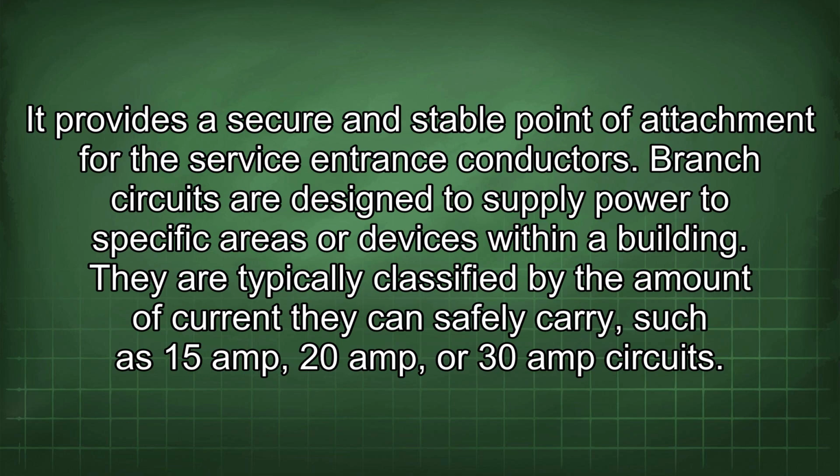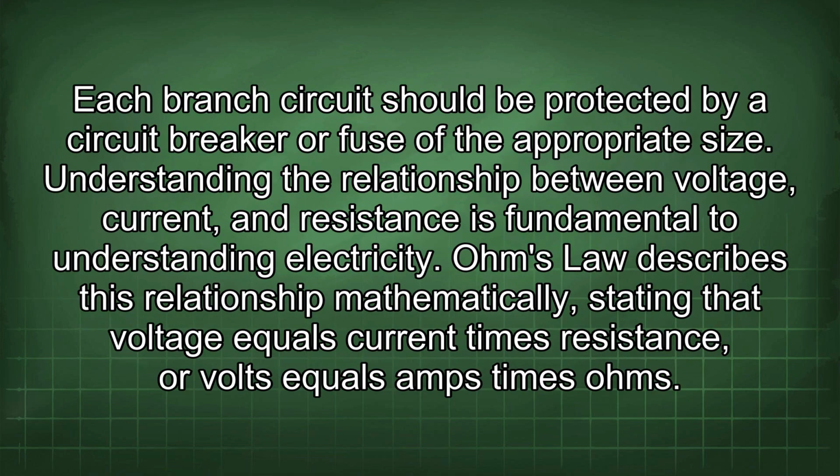Branch circuits are designed to supply power to specific areas or devices within a building. They are typically classified by the amount of current they can safely carry, such as 15 amp, 20 amp, or 30 amp circuits. Each branch circuit should be protected by a circuit breaker or fuse of the appropriate size.